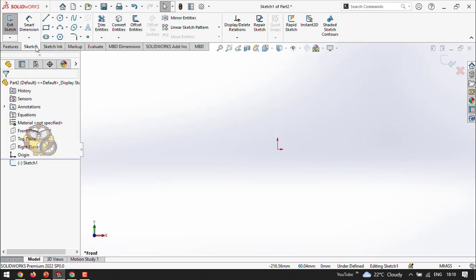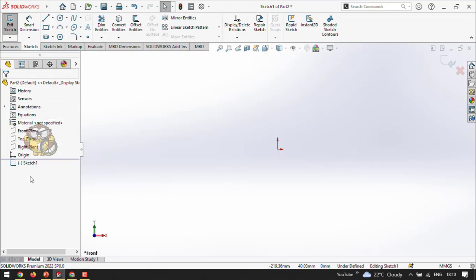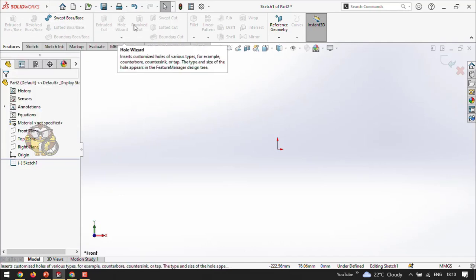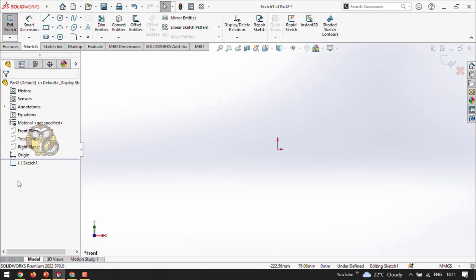Here we have the sketch tools, and here is what we call the model tree, otherwise the feature manager. What features are you going to add? For example, sketch, and next I am going to make it 3D. Here we have different types of features available, like extrude, revolve, sweep. All these features are added here continuously, so we call it the feature manager or model tree. So first you choose the units. Next we want to set the material.